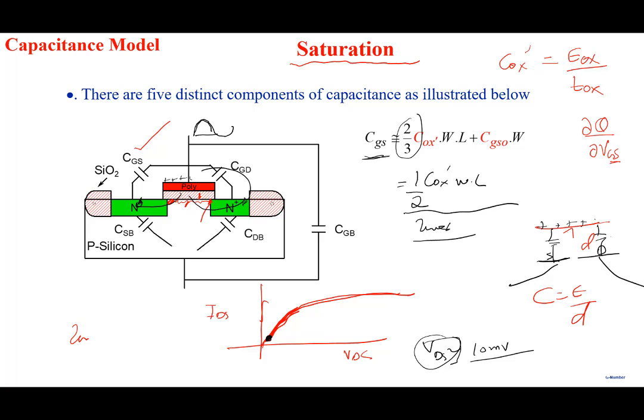So note the complication that occurs. The capacitance in saturation is different, capacitance in linear is different, and then capacitance in cutoff, we'll see in a minute, cutoff will also be different. Right, so these are coming about from the channel region. And this one comes about because this diagram does show it, if you can see here, there is an overlap in this tiny region here. There's an overlap between gate and source, right? So there's an overlap region here, and that gives rise to what is called overlap capacitance.